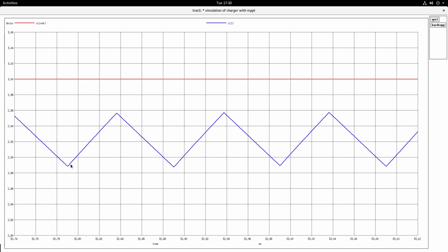Now you see that the inductor current is not reaching up to IL ref. The reason is that we have a slope compensated modified reference which is falling down from IL ref value, and when it is falling down from IL ref value, the inductor current will cross it somewhere lesser than IL ref value and change state, and then start into the downslope mode.